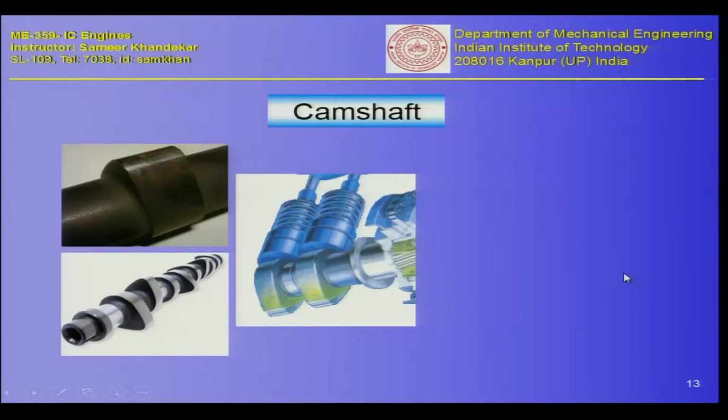Okay. Then we have also discussed how 4-stroke engines, or even some 2-stroke engines, require valves. For example, the large marine engine in the video which you saw in the initial lectures required an exhaust valve which was operated by a hydraulic mechanism. So there are valves which are required for 4-stroke engines, of course, and some 2-stroke engines will also require some exhaust valves or inlet valves. Those valves are operated, and they have to be timed.